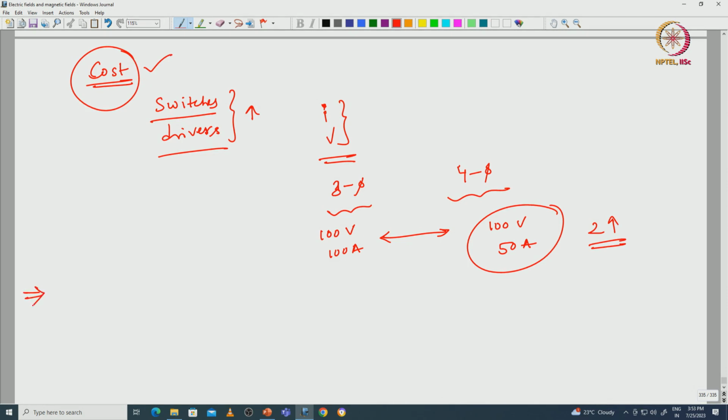After selecting the number of phases with respect to all these aspects, next we have to select the number of poles with respect to the stator. The number of poles at the stator we have to select as per the standards of stator and rotor combinations, like 6/4, 8/6, 12/8, 12/10, 16/12 or 16/10, etc. The stator number of poles should be higher to make a symmetrical rotation, but a lesser number of poles is also possible.